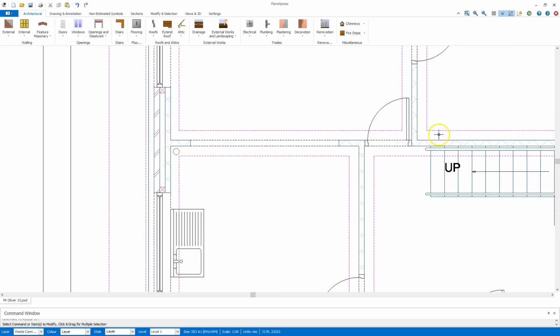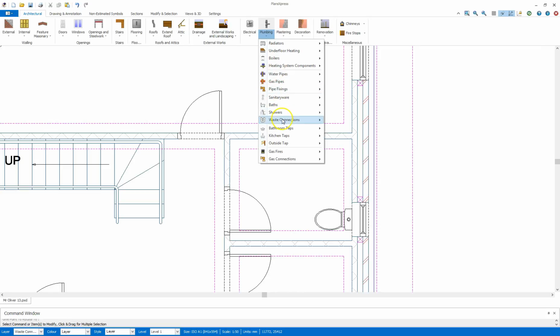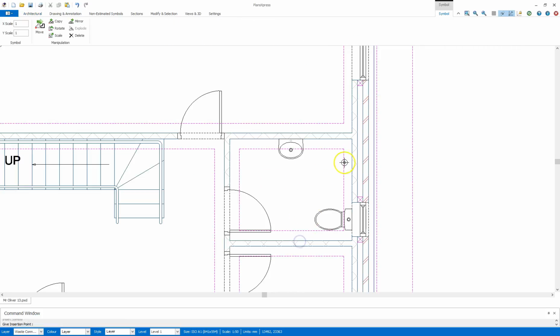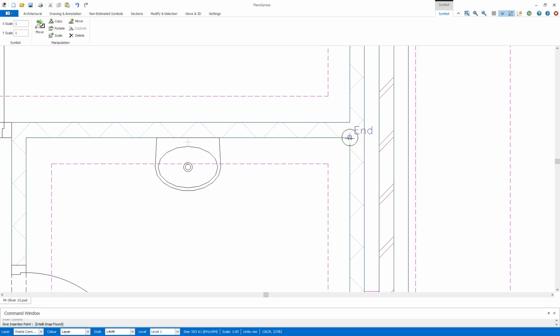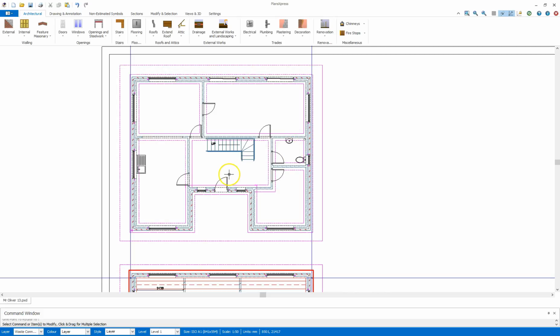Once that's done I can move across to the other side and select the next soil pipe. So waste connections, soil pipe and vent, and select a typical stack. Set the defaults there, hover over the intersection of two walls, press the R key, and this time because it needs to go to the left and down, both will be minus 100. Place and orientation.